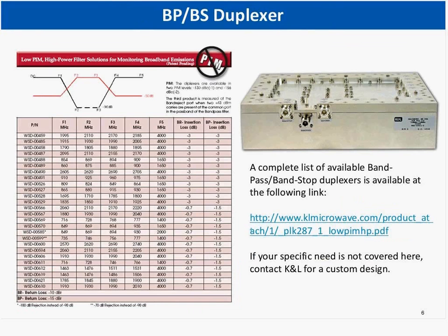More information about bandpass bandstops can be found on this link here. And we have developed bandpass bandstops for nearly all the LTE bands and all the possible combinations within LTE bands. As you can see, this is a cavity filter, and it is handling more than 100 watts, 150 watts CW, and a couple of kilowatts peak with 10% duty cycle.